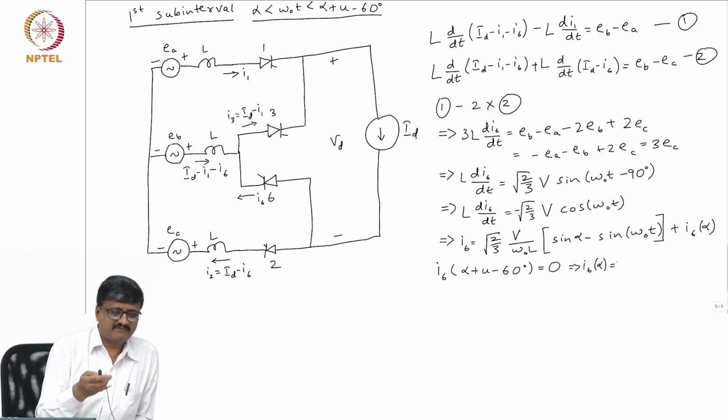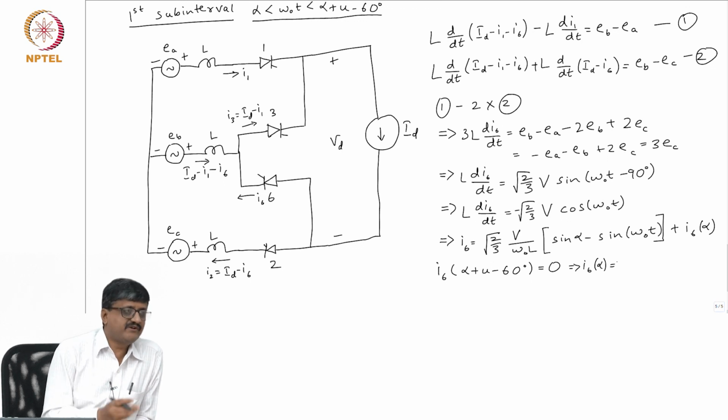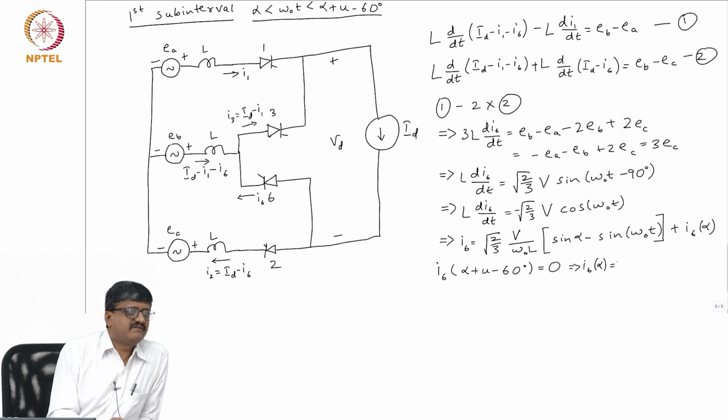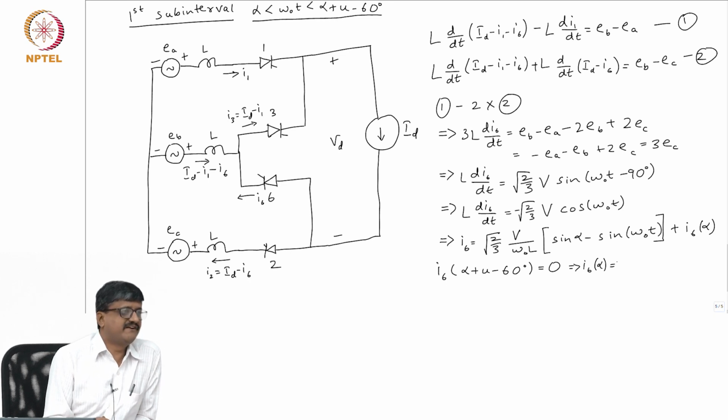If there is harmonic content, we know there is harmonic content. We want to know the amount of harmonic content. Knowing that, what next? What do we do with that? Why do we want to know? Because we need to eliminate. Eliminate how? Finally, we will use that to design filters.